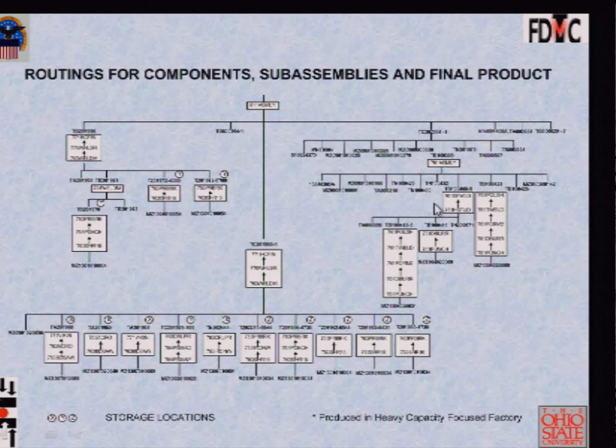Just look at the way the product gets built, and wherever multiple value streams become one, that joint point is where you would put the supermarkets to coordinate and manage kits of parts. So that's, again, I'm not saying that it should be done, but do not merge the value streams when you know that there are critical, unique sub-assemblies.